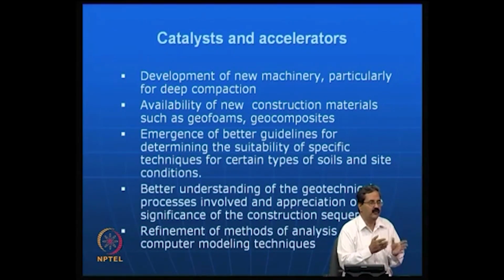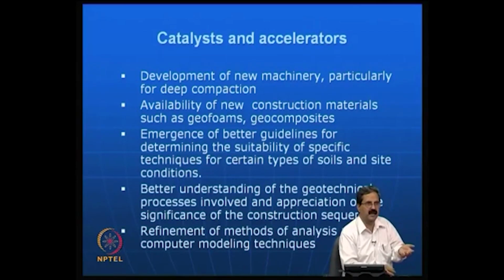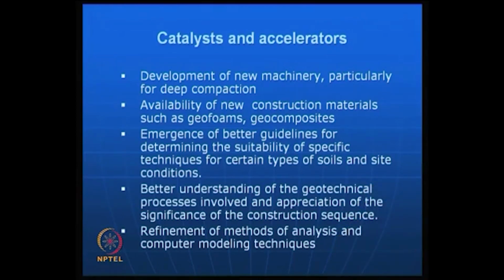If you are doing a sheet pile wall first or some micro piling, first the micro pile has to be put and then excavation should be done. There the sequence is different, because our objective is that there is an apartment here, so put a micro pile first, then remove the soil, because the micro pile will take care of the load that comes. There is a component of load from the foundation of the next building which will cause shear on the micro piles. So it should be taken care of. Once you design it, you can remove the soil here.